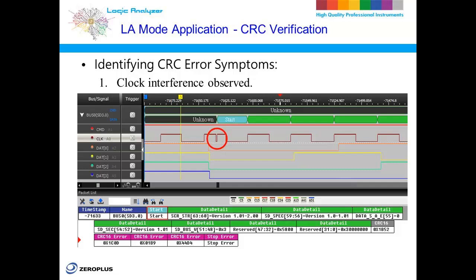Summary of steps to address CRC errors. Check the waveform display to confirm the stability of the clock signal. Add shielding, grounding, or filtering measures to reduce external interference. Verify the quality of the clock source to ensure it remains stable. Calibrate probes properly to guarantee accurate signal measurement.